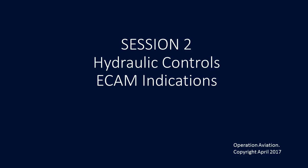So some of the things that you're going to see as far as the way it's going to be worded on the panel is you're going to have your reservoir low level, RSVR LO LVL, and reservoir overheat, OVHT, your reservoir low air pressure, PR for pressure, and engine pump low pressure. So now let's look at the blue.